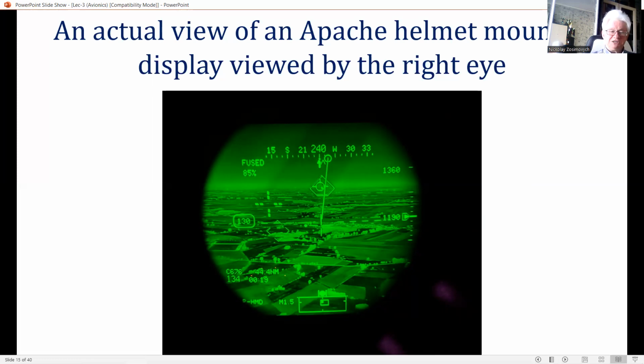The amount of display symbology of a simple sight is generally kept to the minimum, typically an aiming cross or circle and simple cueing arrows, up, down, left, and right, to direct the pilot's LOS to the acquired target, or a detected threat and missile status.